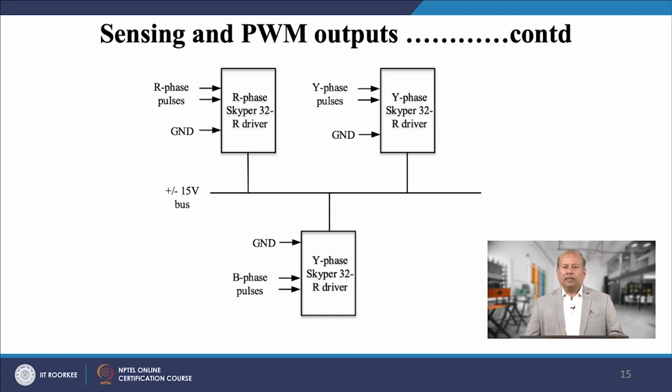Similarly, the digital output pins 3, 4 and 5, 6 are connected to the respective gate driver of that phase. These gate pulses are of 0 to 12 volt magnitude with respect to a common potential, the external DC source negative in our case.